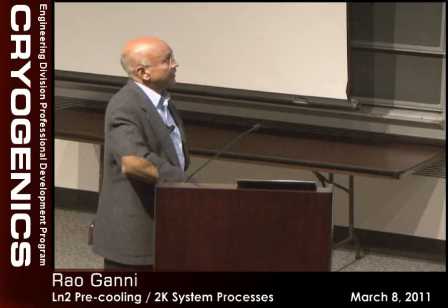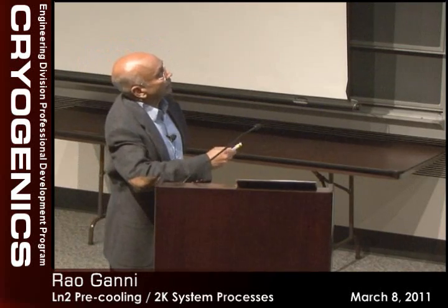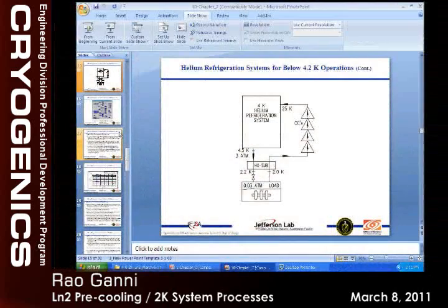Okay, what happens is, this is a thermal link. We are supplying 4K from the cryo module, and we are taking your 2K from the various loads. There are 40 JTs give or take between the front end and the linac, and they're all working in sync, providing a certain amount of load here. And it's not always constant, you have a variation. One JT may be opening, one may be closing. And so there is so much gas on it. For a given temperature here and a given speed ratio we set, it is processing so much flow.